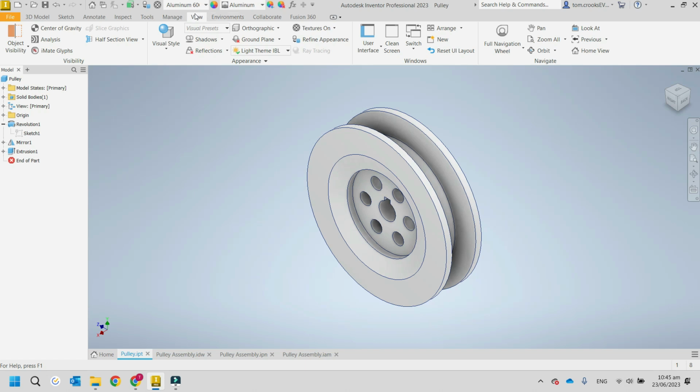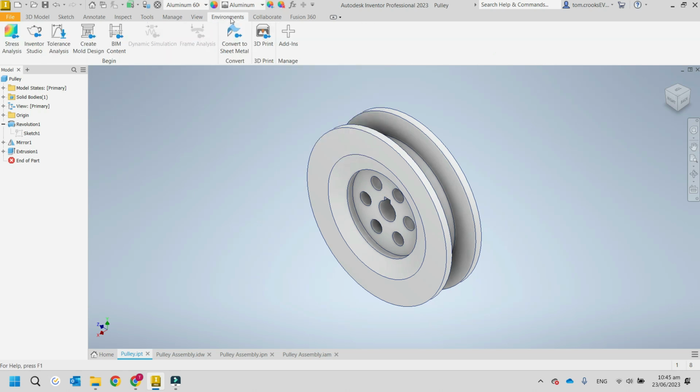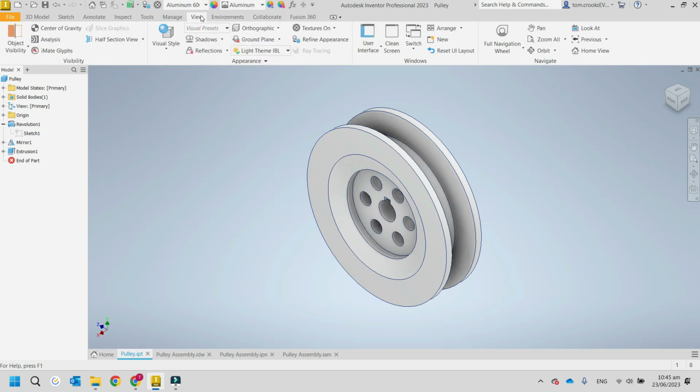Environments. Oh, another thing here. If you accidentally close out of your browser, you can find it here. So go back into View, Interface, and turn it back on. So we've got the navigation bar, status bar, document bar, model browser it's called here. So if you accidentally close this, which happens reasonably often, bring it back up with this one. We've got some further ones which I won't go into. These things are a bit more advanced, but they are there.